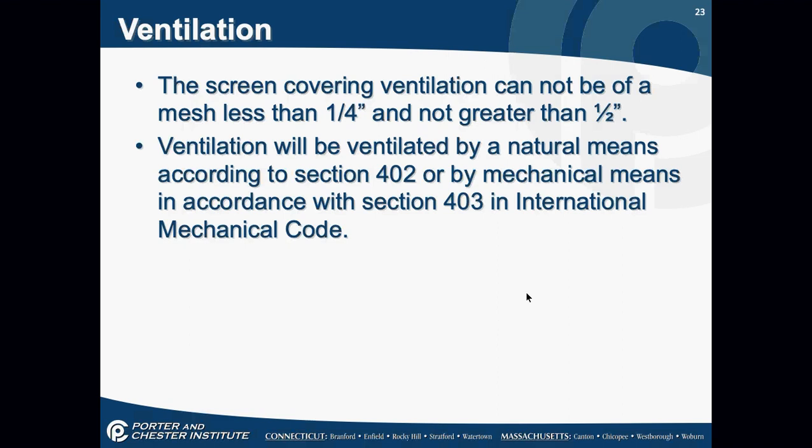What happens in the spring in most areas of the country? What do I have very heavily coming off trees and plants and stuff like that? Yep, there you go. That stuff. The green stuff, the white stuff, that's all over everything. If the mesh is less than 1/4 inch, it's going to get clogged.